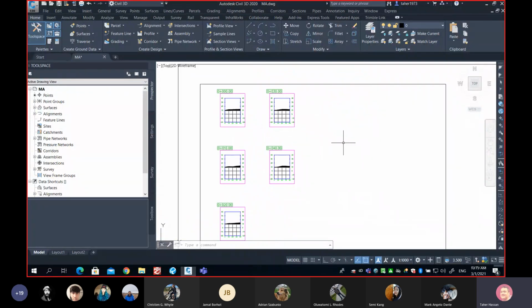Now I know that we don't see the numbers, so I know that some of you will ask, so how much exactly is the cross-section area at 0, at 10, at 20? Those are kept right now in the memory of the software. So you know, the software has already figured them out, so we don't have to do any calculation further, okay? So we know the cross-section area. Our last step right now is to simply show those areas and the volume.